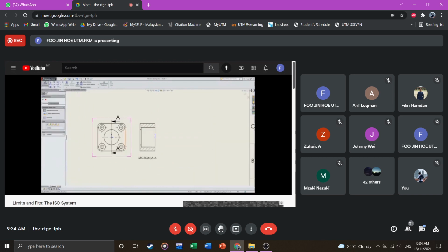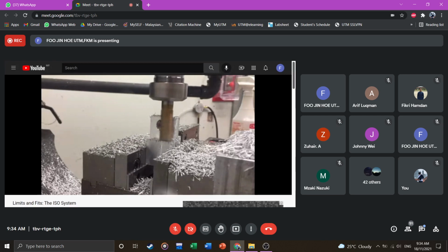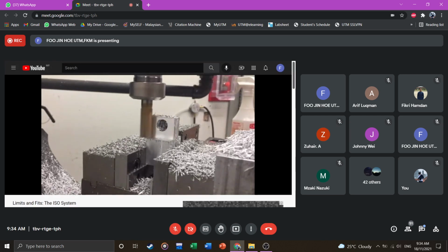So knowing the different tolerance zones and having a list of a dozen or so preferred fits, we should be able to design parts that fit together how we want. We also have a means of vaguely checking if a manufacturing method will be capable of hitting those tolerances. In addition to the oft-used pin and hole example, the system can be used for internal-external parallel faces, such as keys and keyways, or other features of size.